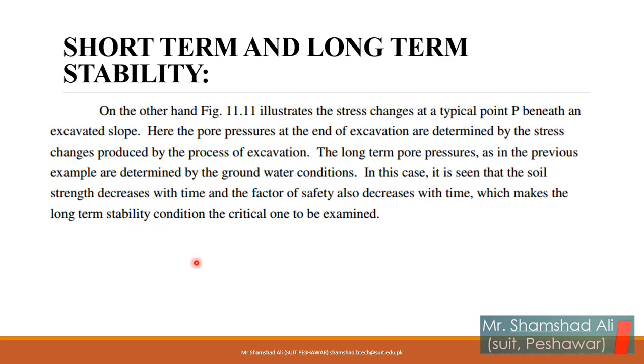On the other hand, figure 11.11 illustrates the stress changes at a typical point P beneath an excavated slope. Here, the pore pressures at the end of excavation are determined by the stress change produced by the process of excavation. The long-term pore pressures, as in the previous example, are determined by the groundwater condition. In this case, it is seen that the soil strength decreases with time and the factor of safety also decreases with time, which makes the long-term stability condition the critical one to be examined.